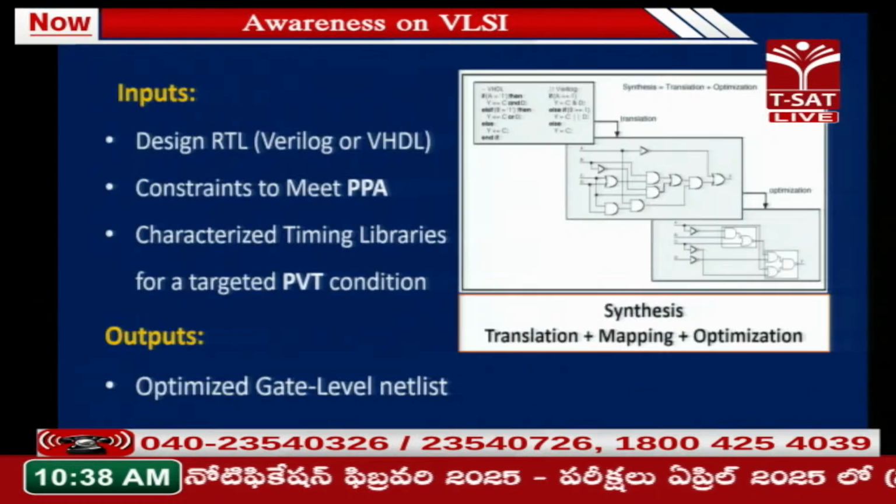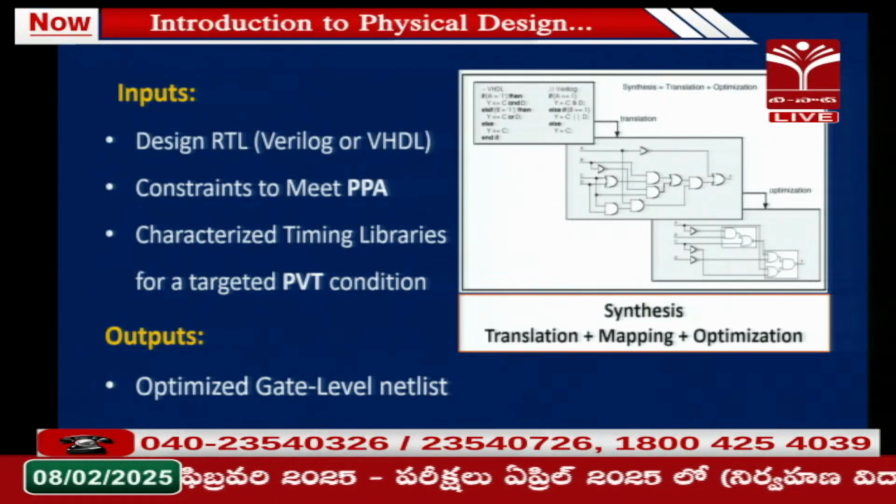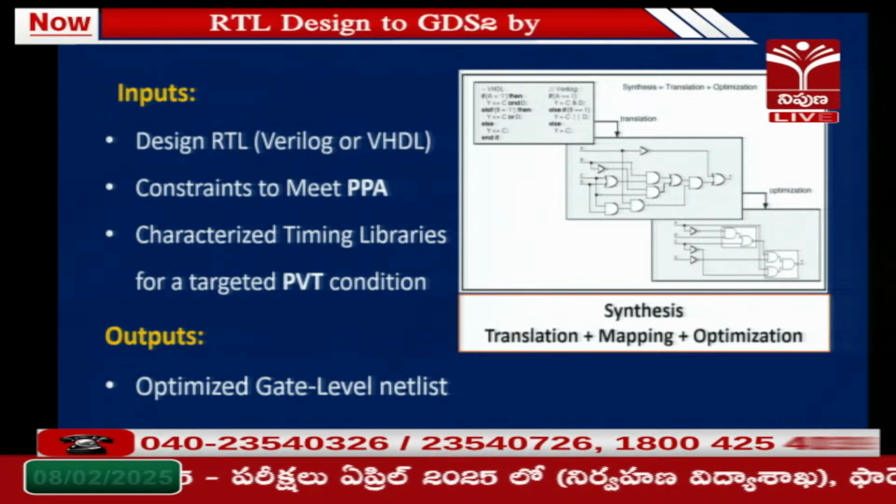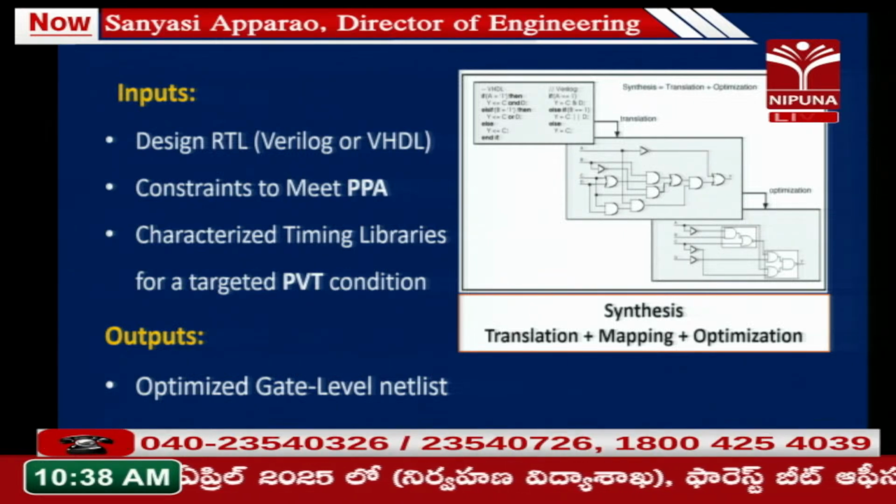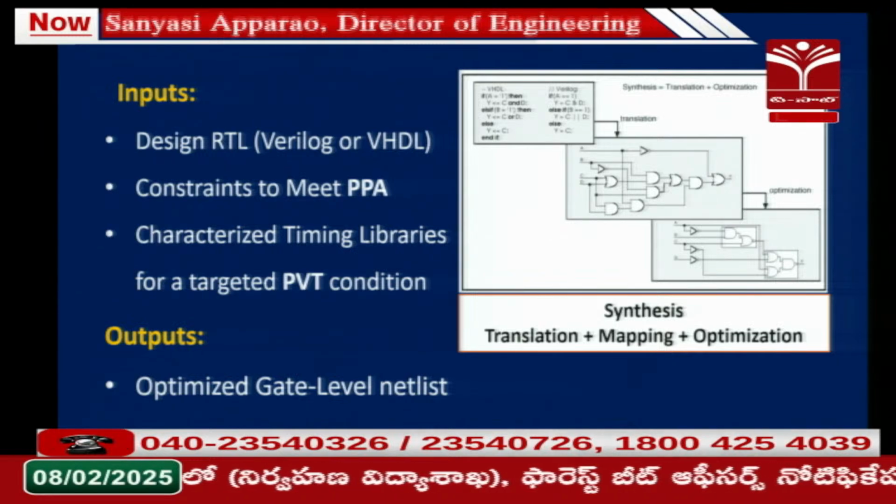As a part of optimization, one is logic optimization and one is cell changes. Logic restructuring is one, and the other is that we can change the cell type. Logic optimization means the same logic, whatever logic you are seeing in the diagram, A to Y, B to Y, all are similar logic, functionally the same, but can be realized using fewer gates. That is called logic optimization or logic restructuring. These logic synthesis tools are able to do that.